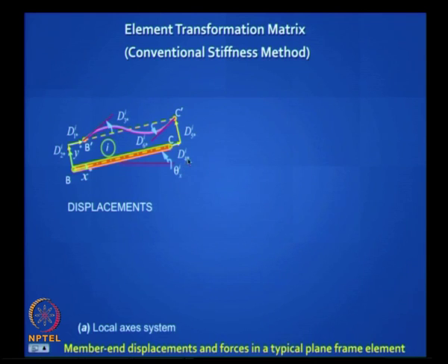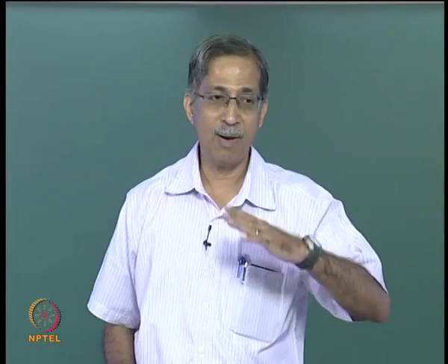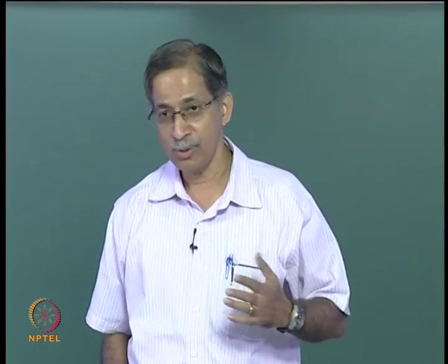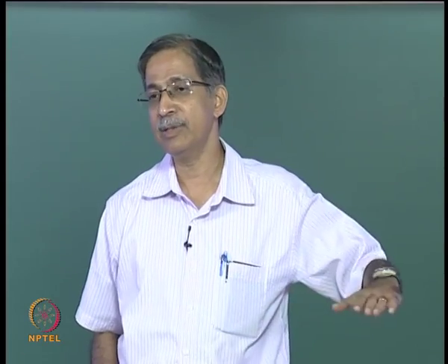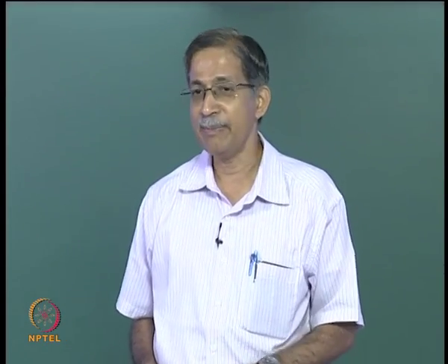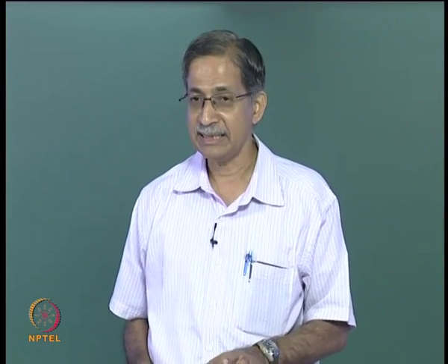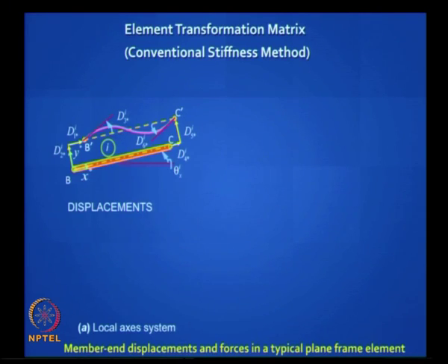Mind you, this theta i that I am talking about here is not referring to a displacement, it is referring to the original inclination of the member prior to loading with reference to the global x axis. Is that clear? So this is what we mean by the local axis system. What do we mean by the global axis system? Okay, this is a similar representation of the element end forces.